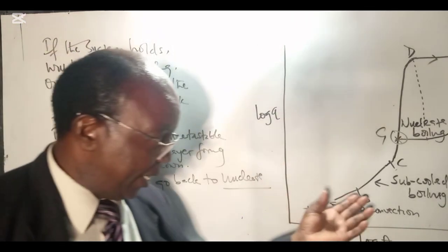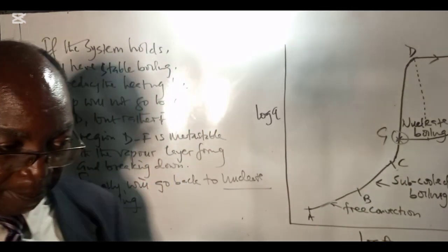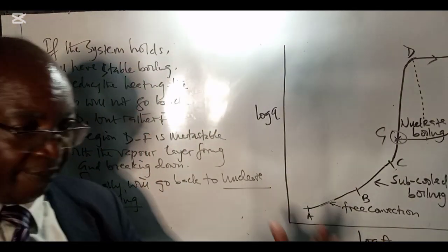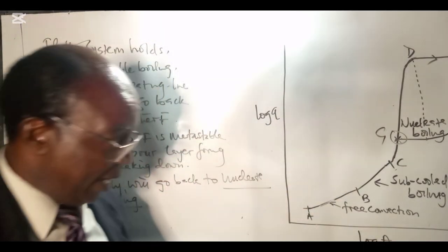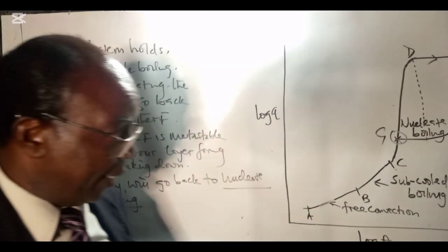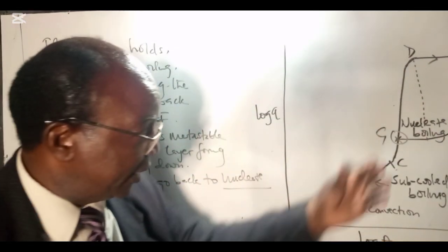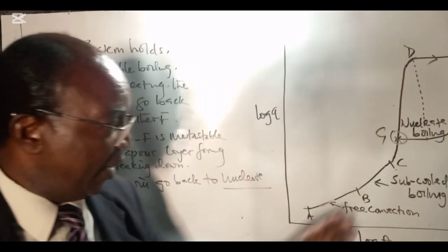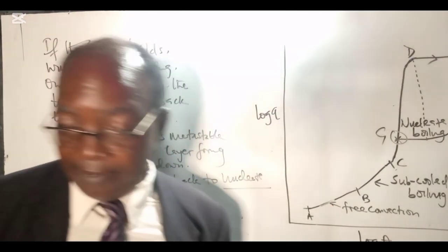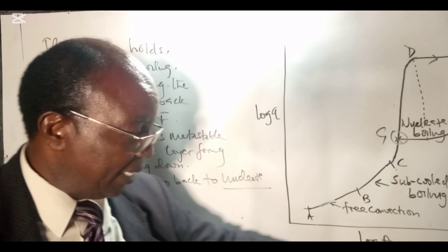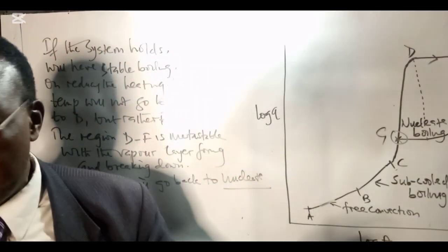And as you increase the heating flux, you have the vapor bubbles, which, as they are produced, also condense because they come into contact with the cold fluid, and that we call subcooled boiling. Then as you continue increasing the heat flux, we start seeing a change in the slope of heat versus the temperature change, remembering that temperature change is the difference between the temperature of the surface and of the bulk.